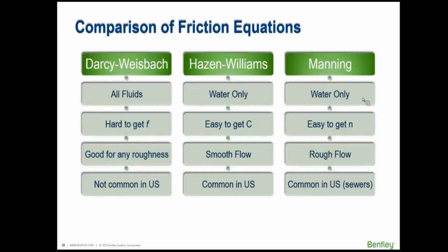Now, in the U.S., not too many water engineers use Darcy-Weisbach. Overseas, we see it used a great deal, but we've just gotten used to Hazen-Williams, which is the most commonly used one in the U.S. Manning's you see more in sewer-type flows.